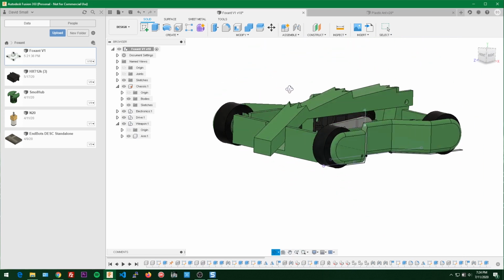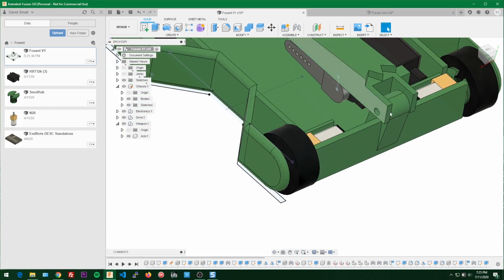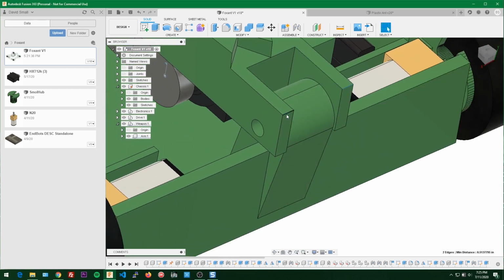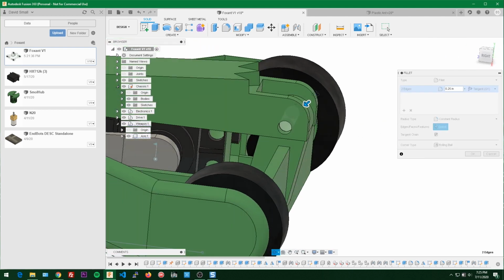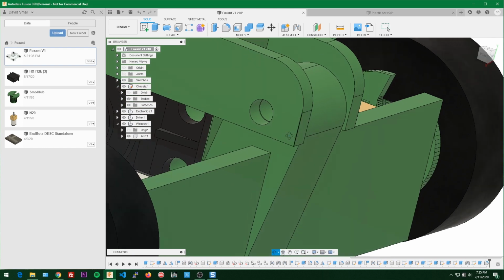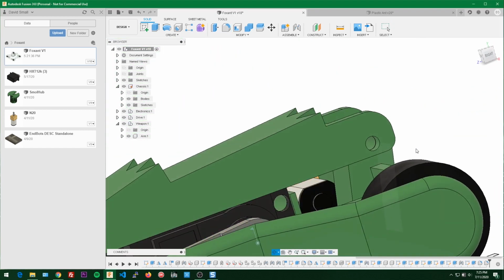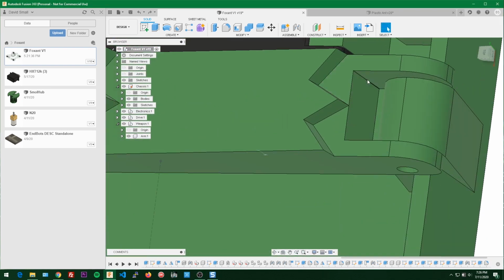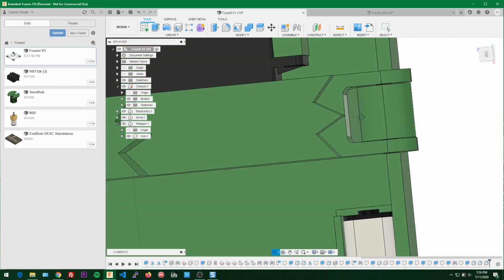And it's starting to come together, starting to look like a fighting robot. And just to pretty things up, let's add some fillets to these back edges. These two. So maybe 1/4 of an inch there. And like an 1/8 inch here. There we go. Rounded edges always look nice. And then for a little bit of additional strength, let's fillet these inside edges 1/16 of an inch there. Cool.